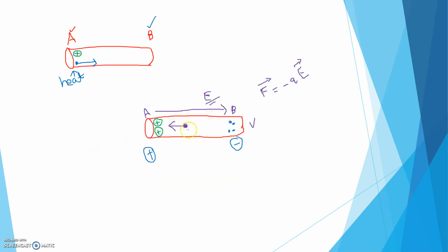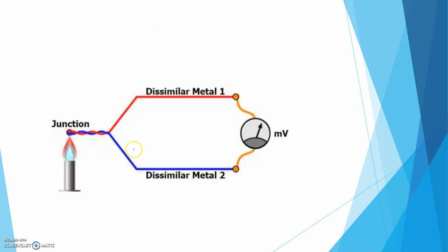Suppose the resistance offered by a particular metallic element is high compared to the other metal, although metals provide less resistance, then the electrons cannot move much, right? So the movement of electrons depends on the physical property of the metal. So how much voltage is generated depends on the metal. In a series connection, if you provide the same heat to two different, dissimilar metals, a different amount of voltage is going to be created at these two terminals. This is very important because their physical properties are different.